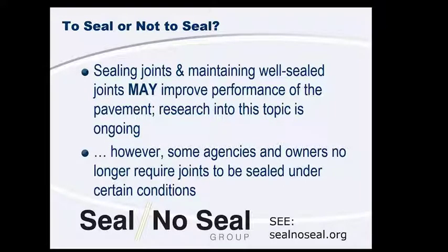If you are sealing joints, however, they need to be maintained throughout the life of the pavement. You don't want to seal your joints and then leave that sealant in there for longer than it's recommended or for longer than the life of the sealant. You are going to have to replace it at some point within the pavement's life to make sure that it's performing the way it's supposed to. Once the sealant reaches the end of its life, it can actually start letting in water. It can also let in incompressibles, and then the water doesn't have a place to evaporate out to. So if you have seals, make sure they remain sealed.